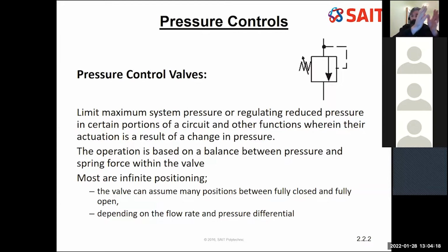And then we will bring that press back up, we'll cut the stake, and then we'll release the clamp that may be holding the steel, and run the motors to extend the next piece of steel. So I've got a sequence of operations here that may be operating at different pressures. I may want to clamp the metal or cut the metal with different pressures depending on which metal it is, if I'm using a stainless steel or just plain old galvanized steel. So we're going to set the different pressure controls in our system.